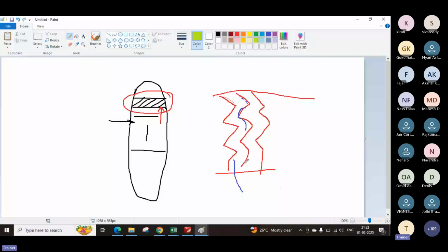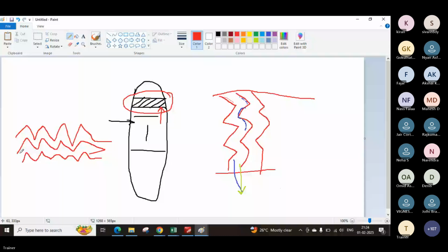When you have a horizontal one, this vane pack is generally like this. Whenever the fluid comes in, suppose this one is coming, when it hits here, the liquid particles will accumulate in this zone and form a bubble or very high drop, and they will form here.